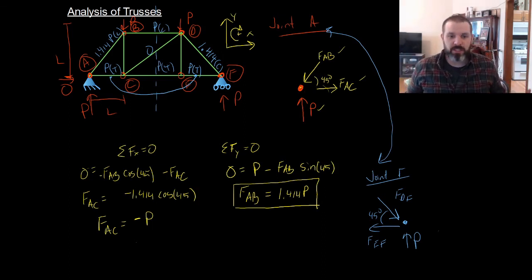The solution of trusses is nothing more than writing equations of equilibrium, summing forces in the x, summing forces in the y. The fastest way to implement this is using a section cut, and a section cut is really useful when you're cutting 3 members. If you're not cutting 3 members, a section cut isn't really useful at all. So whenever I can make a section cut and cut 3 members, I do it. Whenever I can't, I move to looking at the joints, because at the joints, you get 2 equations and you can solve for 2 separate things. Solving a truss is nothing more than writing and solving equations of equilibrium, and using section cuts, writing and solving equations.